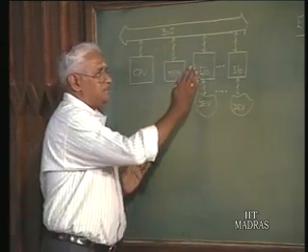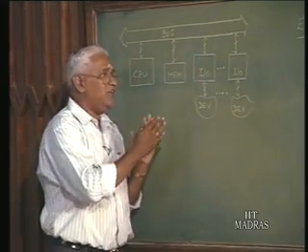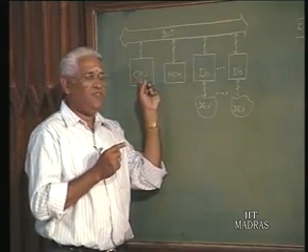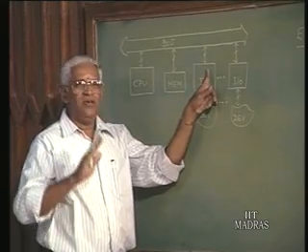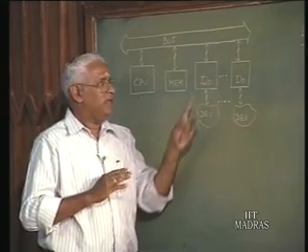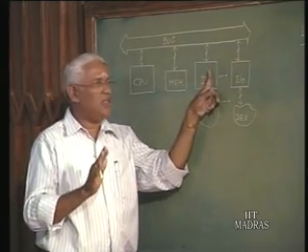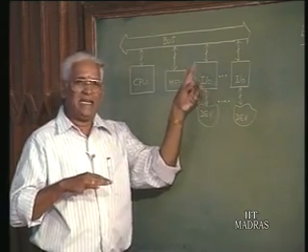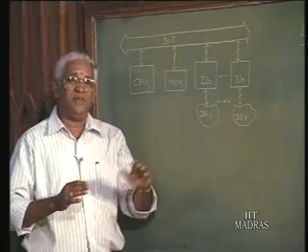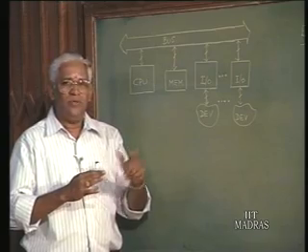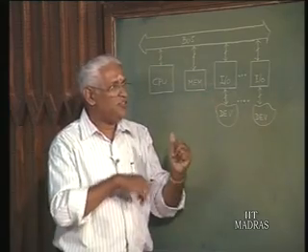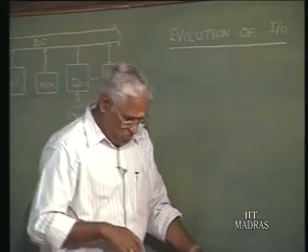Okay. Now, you can see that the sophistication of IO has been increasing, right. Earlier, in the programmed IO, it was enough if the CPU just checks that, and this is a passive one, right. It will only respond to the processor. Then in the interrupt case, it became active, in the sense when the device says it is ready, it will actively inform the CPU that it is ready. And then in the third case, we saw that it became really more active. How? Not only does it inform the CPU, it also takes over the function of the CPU. So, that is why I said the evolution of I/O is a nice thing we can talk about at this point in time.